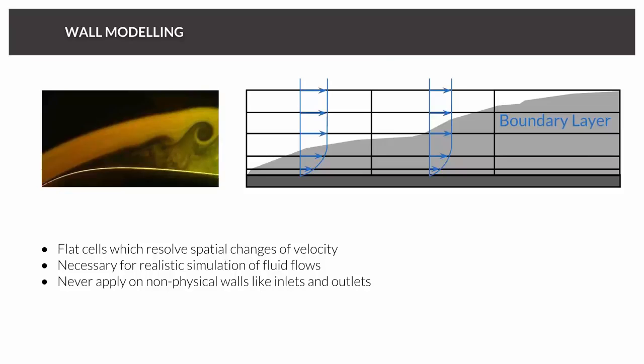So what is wall modeling? Well, as you can remember from last week, where René explained that there's a boundary layer where viscous effects are dominating, and there is an outer layer where we can actually neglect viscous effects. And the big difference between them is that inside the boundary layer, since we have these viscous effects, the flow speed is lower than the inflow speed, or the speed at the inlet. And there are different criteria. Usually, if it's lower than 99.8% of the free stream velocity, it's part of the boundary layer.